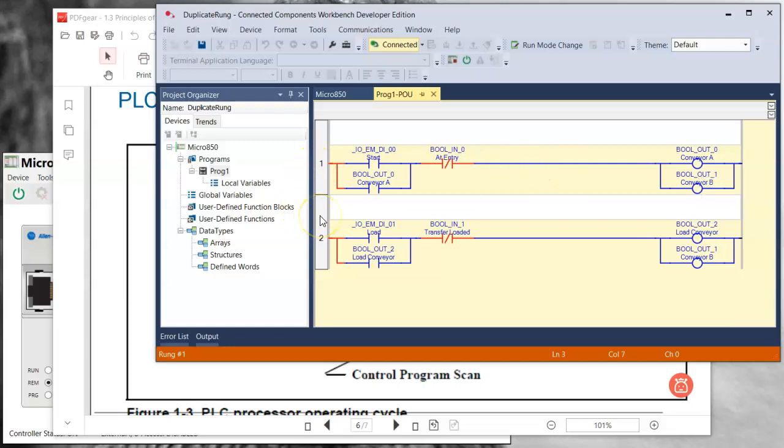Then it goes to the next rung, rung 2, and scans across left to right. Does the same thing. We've got a branch here, right? So it tries to go this path. It finds no way, there's no path all the way to the coil. It comes to the branch and finds no path. So these two coils are therefore turned off as well.